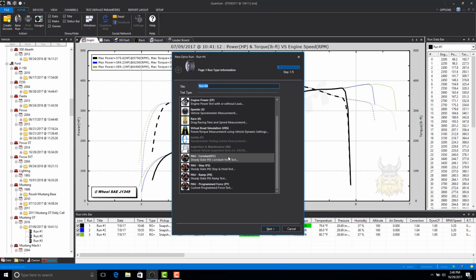And I'll take a sidebar here and say that the way Quantum works in these PAU modes is to send parameters to the handheld/DC controller that are used for the running of the test. So think of Quantum being the master of ceremonies, the controlling agent for the test, but in these PAU tests, the down and dirty manipulation of the eddy brake, the monitoring of the speed, the feedback loop. The closed loop part is all happening between the DC controller and the eddy brake and load cell.